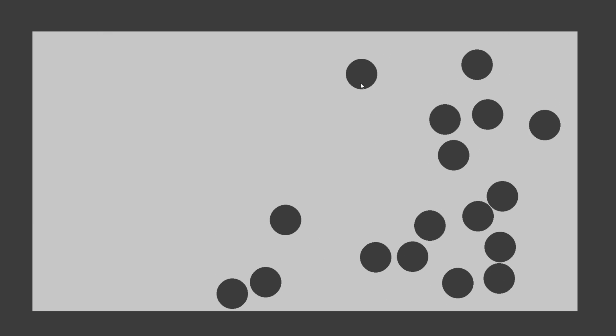Due to floating point errors, objects can sink into each other. This is where the penetration depth comes in. We simply move objects a percentage of the penetration depth away from each other along the axis of collision. With that done, the basic physics engine is complete.